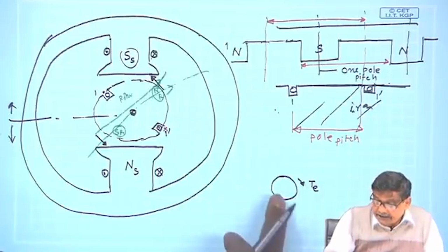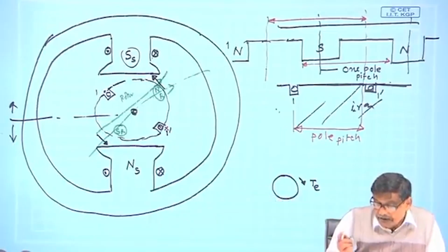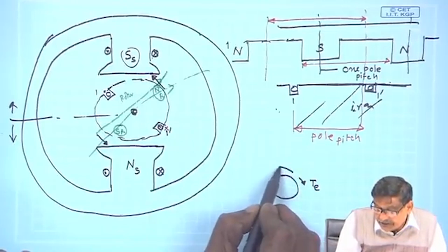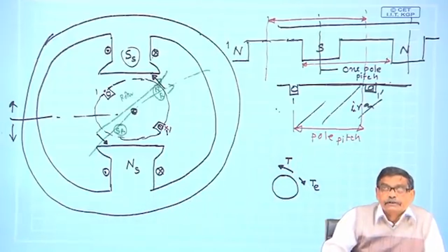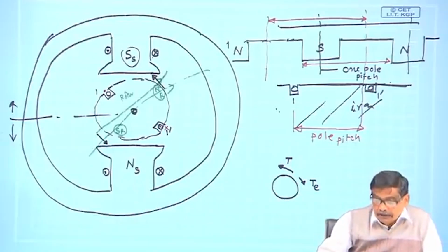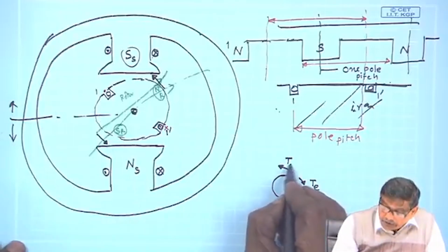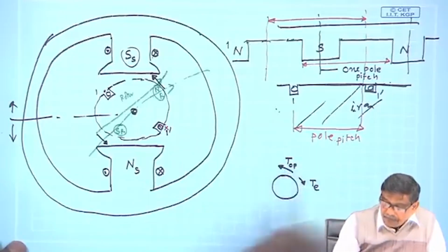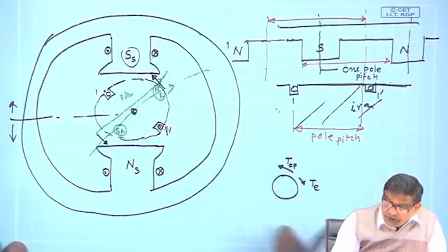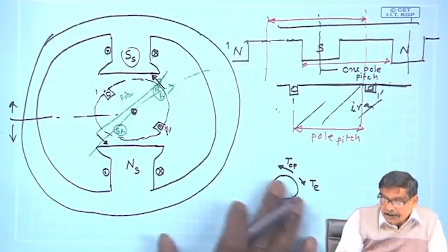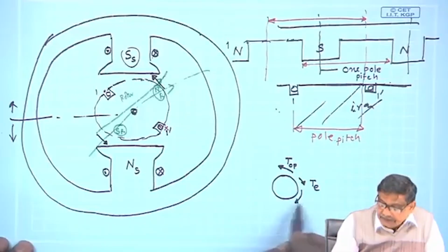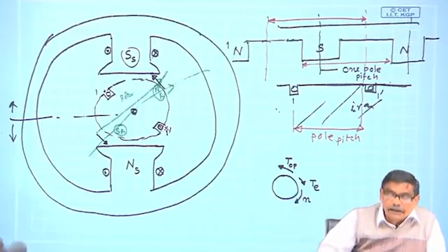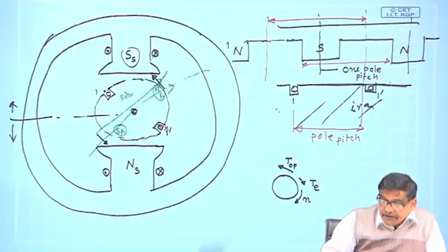And if somebody says it is running at a constant speed, I will demand that on the shaft there is some opposing torque present in the form of friction. The blade of the motor has to run against wind. So, that is the opposing force. Initially there was an imbalance in these two, that is why the machine accelerated with some RPM n, and eventually